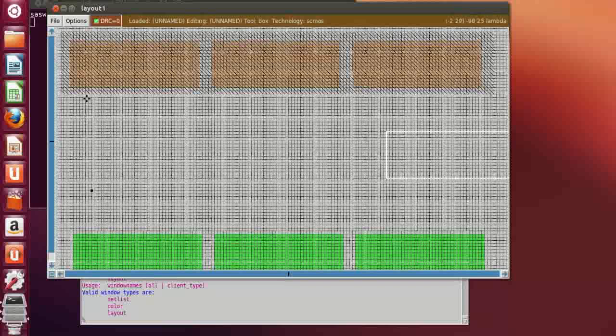Now we know this is one transmission gate consisting of 1 PMOS and 1 NMOS. This is the second transmission gate, NMOS and PMOS. This is the inverter. We are designing a 2:1 mux using 2 transmission gates and 1 inverter. So if I want to design a transmission gate, I have to short the sources and the drains with the help of metal layer.